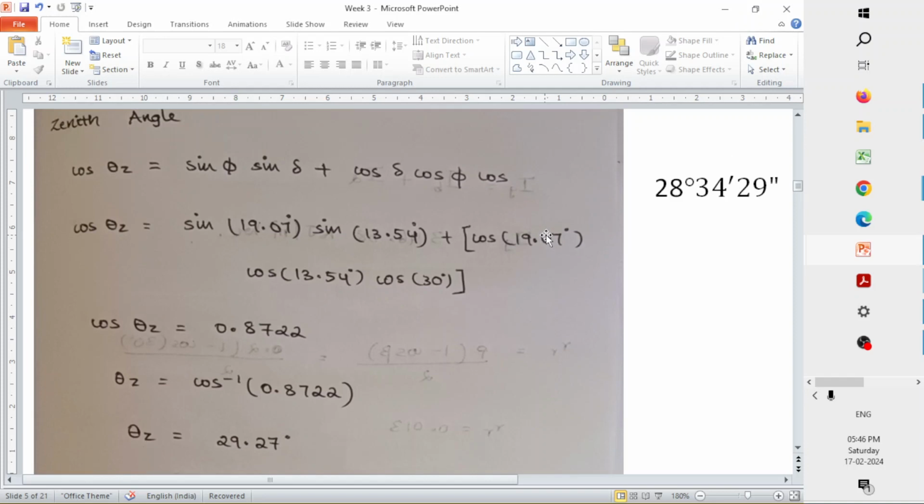If you have a pyranometer and a pyrheliometer in the place where you are going to construct a flat plate collector, you will get these values. It's kind of a recording instrument. So you know your IBN from the pyrheliometer, and from the pyranometer you know your value of Ig. If you know IBN and Ig, you can calculate the beam radiation IB and then your diffusive radiation.